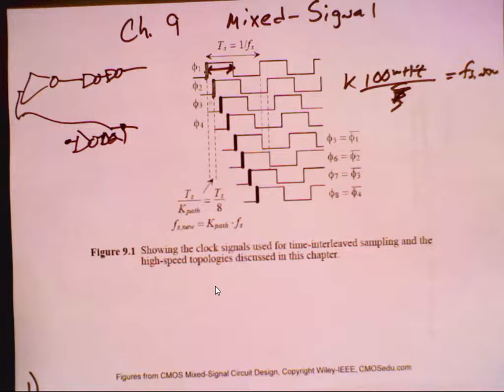Close. The integrator is going to saturate, right? The integrator is going to overflow. If you let the signals go a long time without changing them, the integrator is going to charge up. So you have to change your integration capacitance or your resistances to larger values so the output of your integrator doesn't saturate. That's the level of question I'm going to ask.